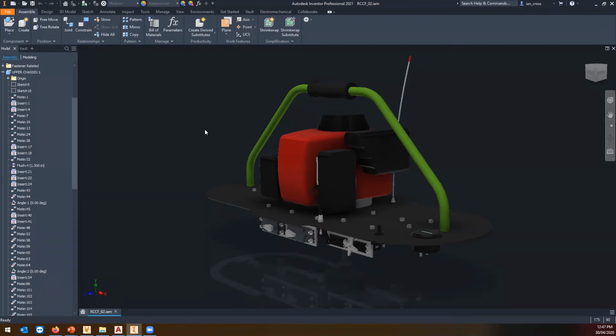One being what's called the ADMS, the Autodesk Data Management Server, which is the server side of things. Vault is recommended to be installed on a dedicated server. And that's where all your files will live. That's where the database will live. That's where the Microsoft SQL database and the file store will live, along with the server console that manages all of that.